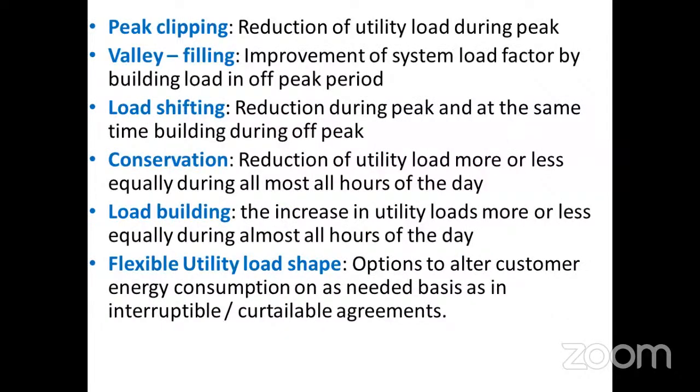What are the different types of load curve variation? Load curve management. One is peak clipping. Peak clipping means the top load, just as I told, cutting off the load during peak hours. Valley filling means raising the load during non-peak period so that the system load factor will get improved.